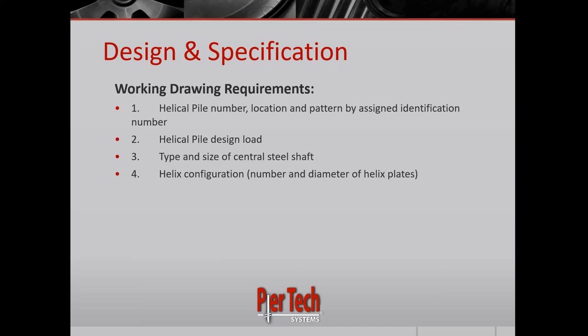Then you have the helix configuration. We talked about that earlier. So you've got your single helix leads, double leads, triple leads. So that configuration, the number and the size of those helix blades will be written on the working drawings.